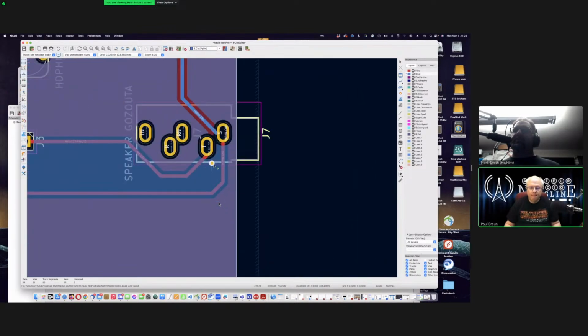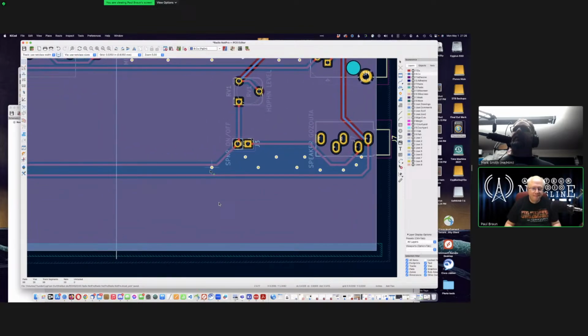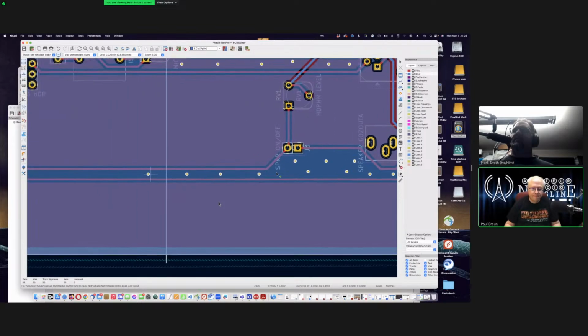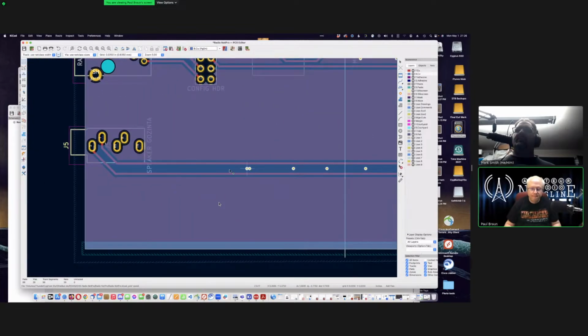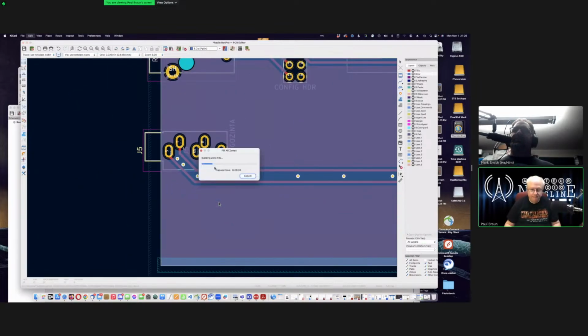fill in a bunch of vias elsewhere. And I'll show you some other things to look at for via stitching and filling. Yeah, that's pretty dense. You don't need to go that dense. I mean, it's okay. Don't delete. Never mind. Yeah, that kind of density is fine. And then drop some on that big one. Yes. Yep. All right. So those are good.